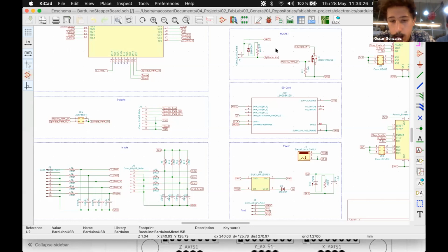And it's already protected with a flyback diode and everything, so that you don't damage the board. The only thing is that we don't have enough control pins, so you will have only one PWM that will be translated either into a 5 volts output PWM, a 3 volts output PWM with a level shifter, changing just the voltage level, or the MOSFET output. But they are all the same PWM, only in different voltage levels, okay?